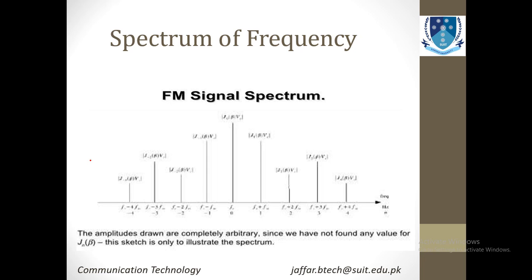But up to this point in the course, assume that you have the ability to accept or deny. So you will have to place a significance threshold. If the energy of a sideband is above that given threshold that you have fixed, you will accept that sideband, and if it is not, you will discard it and say that it is not significant. Those you accept are termed significant sidebands. I hope that this justifies the concept of significant sidebands.